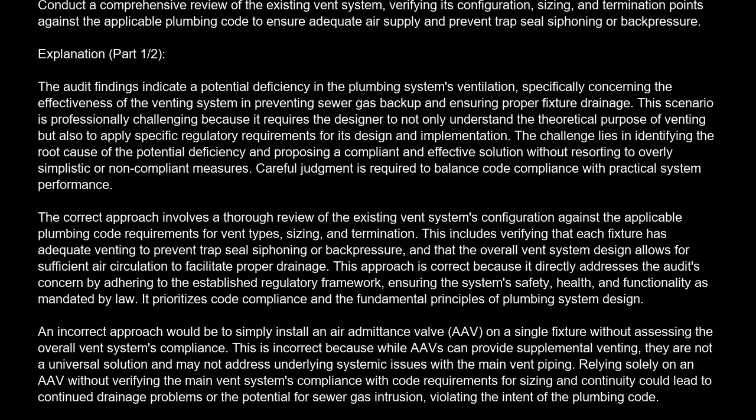The correct answer is D. Conduct a comprehensive review of the existing vent system, verifying its configuration, sizing, and termination points against the applicable plumbing code to ensure adequate air supply and prevent trap seal siphoning or backpressure.